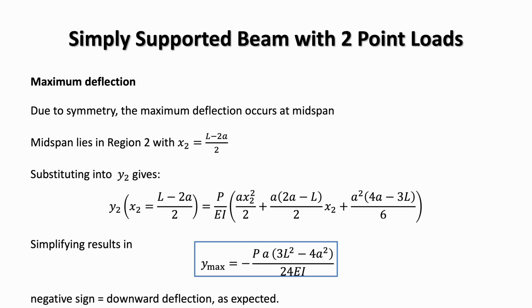You can see here that the structural solution included identifying the regions, finding the bending moment for each region, then integrating that twice and having constants of integration, which we solved for using the boundary conditions and continuity conditions. Now that was the whole structural thing. The long part here was the maths, the solving of 4 simultaneous equations. But hopefully that was all clear.